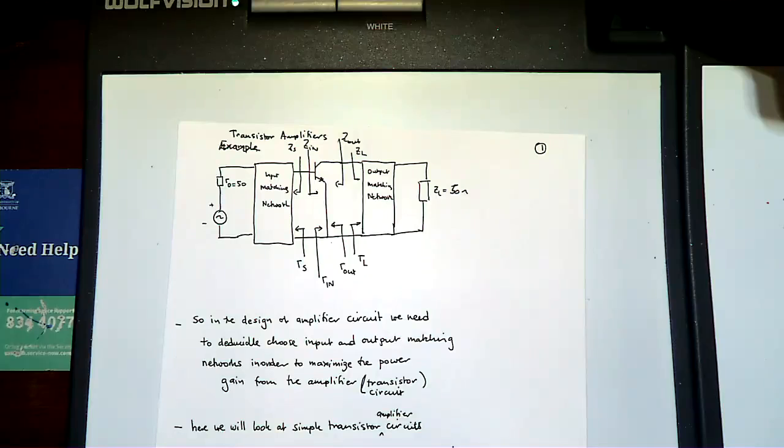if I draw this symbol for an ideal op amp, this relationship, the gain, which is R2 on R1, hopefully minus R2 on R1, applies for all frequencies, right? If it's an ideal op amp. Correct? Yeah. What dictates what frequency I can actually operate this at?